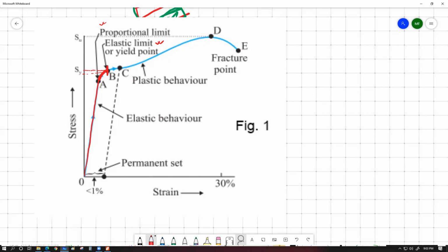So that point is in the curve, but this much behavior is the elastic region, and from there further to the right, all the way up to here, this is what we call the plastic region. Plastic region means that object will not behave elastically. Object will have some permanent deformation stuck within itself. And why we measure permanent deformation, I'll show in a different way, but is the difference between these two points understood?